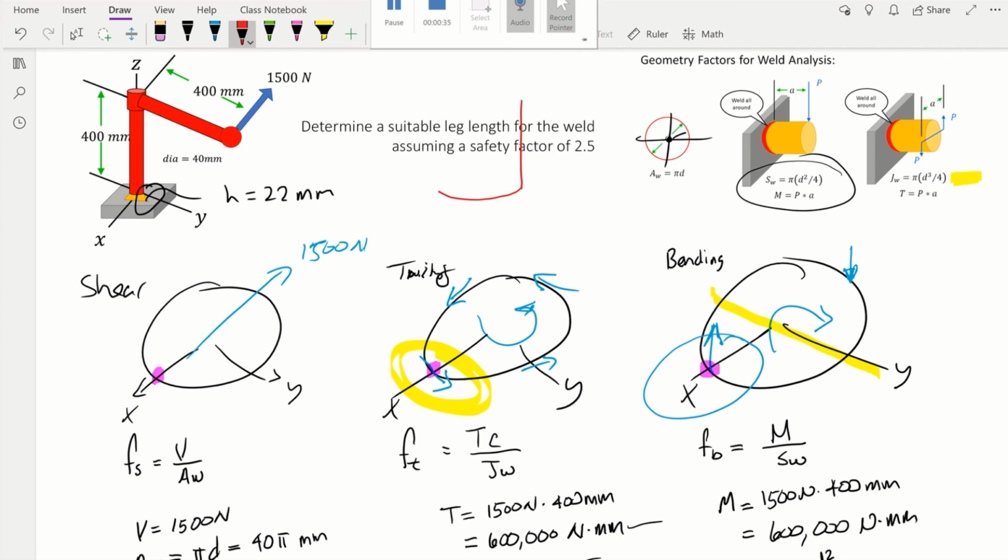It's gonna be lying on the plate, and so that weld, let me go ahead and do it in green, has to be 22 millimeters high and 22 millimeters here on length. And hopefully when the weld gets deposited, it's done correctly and it's gonna look concave like this. And again, this is 22 as well as this distance is 22.